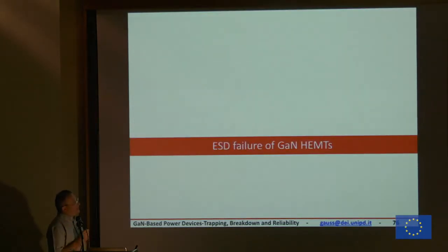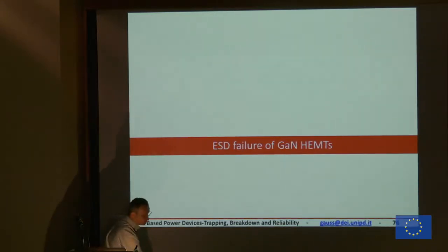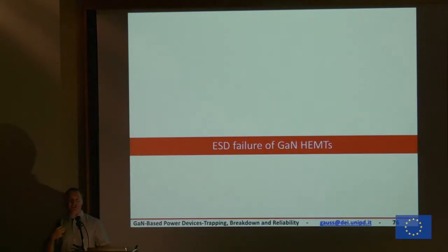Okay, I will leave this slide for you for the future. I'm not going to get deep into this. It is ESD failure, electrostatic discharge. It's more of a qualification procedure, just to tell you that in general some overvoltages for short times may happen, and you really need to design your circuit to guarantee that if you take your system with your hands and you are charged because you are working on a linoleum carpet or whatever floor, and you discharge, you do not destroy your device.